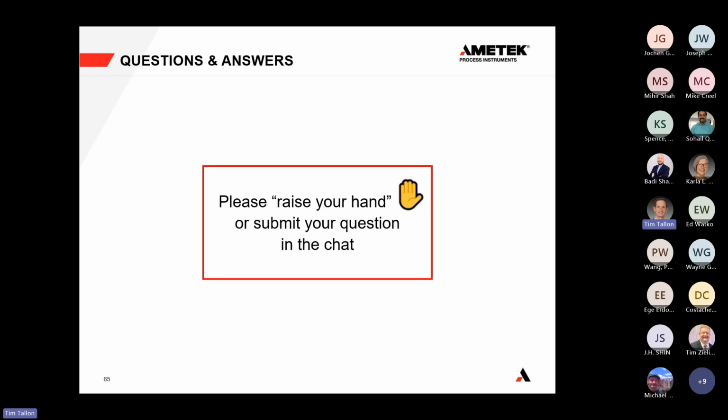That's just roughly what they've noticed as a good rule of thumb for fired heaters, around 500 ppm, just to have a first pass alert for approaching combustible breakthrough. So that's around 500 ppm, and that's again the first alert, the first high combustibles interlock. The second one is the high combustibles shutdown, and that's when it exceeds a certain value.